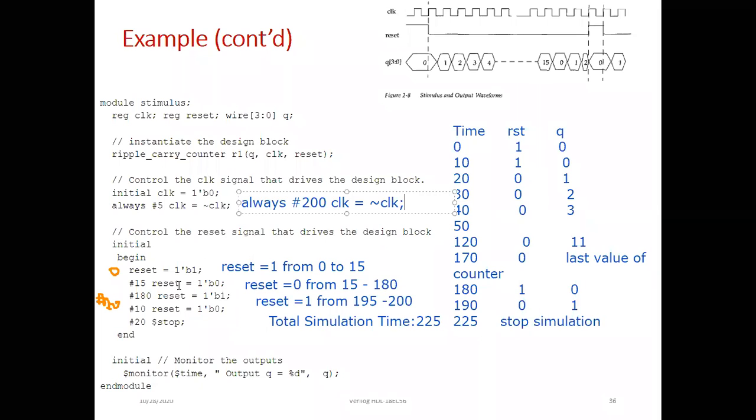Now what will happen here? The clock period time is 400, but all the operations will be complete within 400 itself. Now Q value will not change at all. Why? Because reset goes 0, reset is 1, everything is happening within the one clock cycle itself. So this is your one clock cycle, and whatever reset change, 0 or 1, happens only at the edge, positive edge or negative edge.